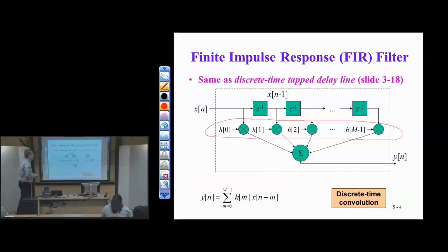So let's take an averaging filter, and we'll do the normalized one. For a normalized averaging filter, we can draw the same block diagram. I average the current input value with the input one sample ago. So that I can write as a tap delay line.